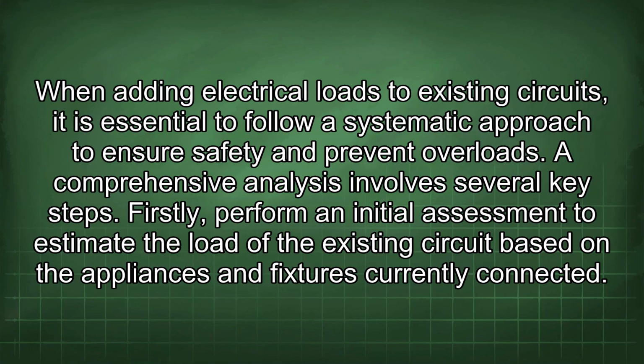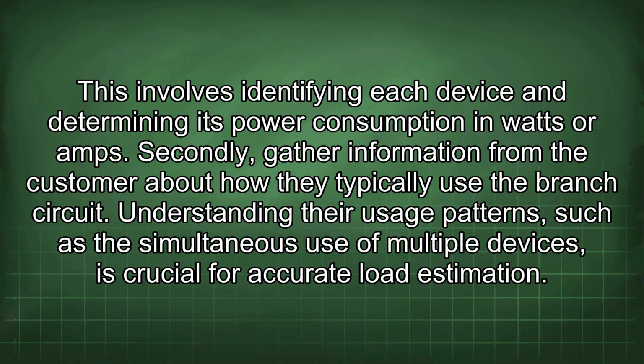When adding electrical loads to existing circuits, it is essential to follow a systematic approach to ensure safety and prevent overload. A comprehensive analysis involves several key steps. Firstly, perform an initial assessment to estimate the load of the existing circuit based on the appliances and fixtures currently connected. This involves identifying each device and determining its power consumption in watts or amps.